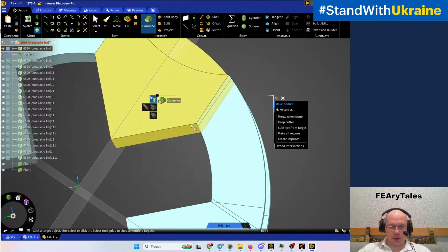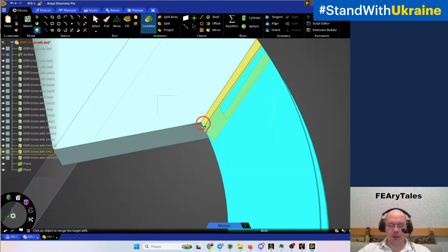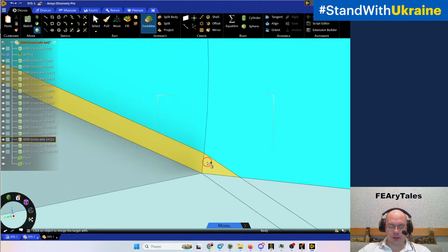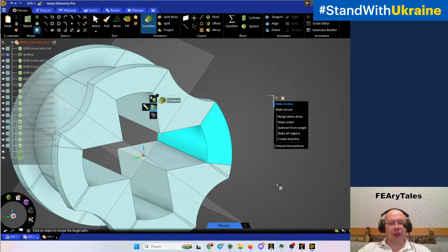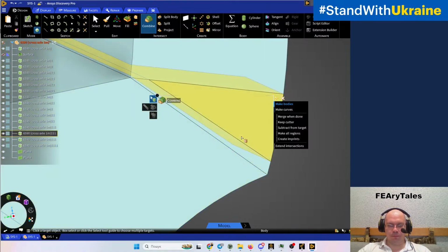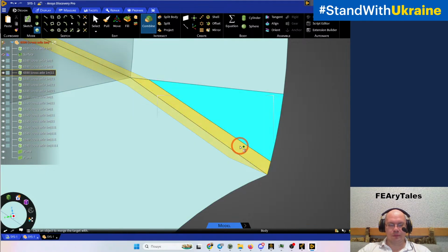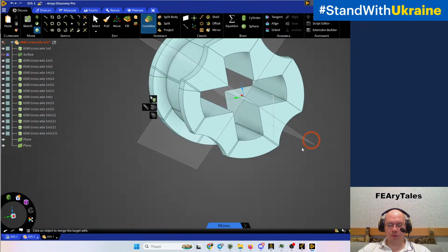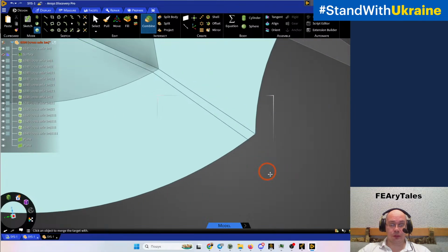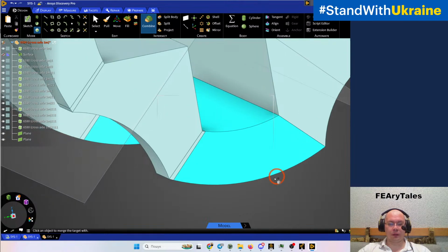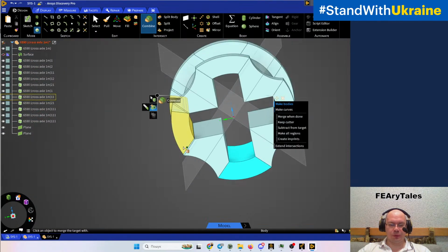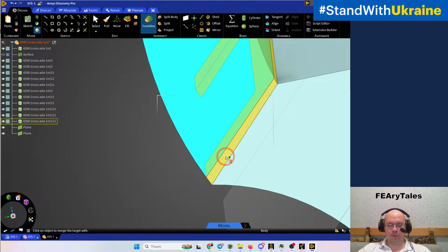Sometimes it's a simpler way to split not in Discovery or SpaceClaim, but in your native CAD, because, for example, SolidWorks has the possibility to split with a complex shaped sketch. So if you have a license for SolidWorks and your geometry was created in SolidWorks, maybe it will be a simpler way to do some splits in SolidWorks.